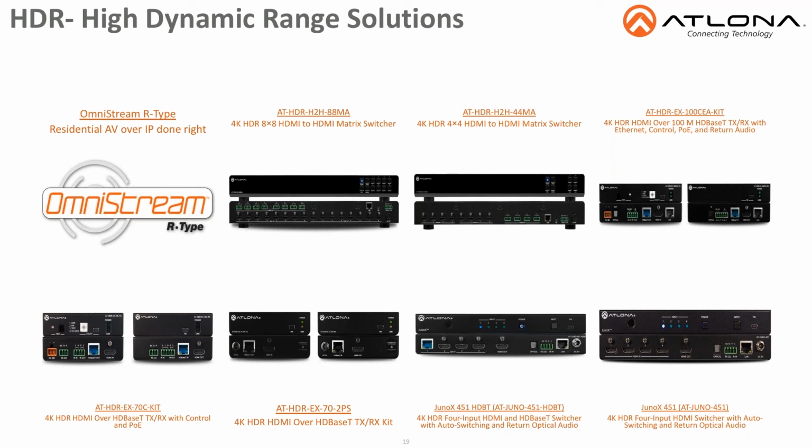And if you need to extend with the Juno, if you notice that any of these Juno have a blue port on that HDMI, that means that it will also serve 100 meters. So on a lot of our switchers, those will extend up to 100 meters, and then the receivers will receive the same thing, not just transmitters, receivers. I never knew the color code. See, I'm learning something as well. Yeah, that's perfect.